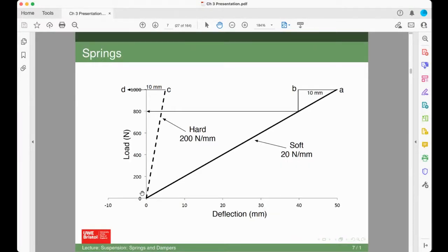And obviously this load, divided by the unsprung mass, gives you an acceleration force into the ground. With the hard spring, it runs out of travel at 5 millimeters, and so the wheel will only go into the depression through gravity, or it skips over the depression, depending on how big the depression is. That's why you want a soft suspension for traction, because with any imperfection in the road, you're still providing a lot of input into the road to unlock the grip.